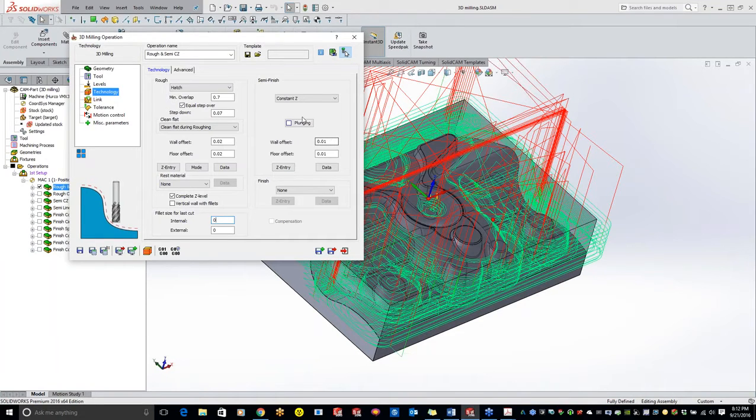Now when you guys do semi-finish, you have a lot of options in here. Doing linear, and as I click through, you can see the pictures change. We do offset cutting, we can do spiral, and I'm going to go through all these operations. I set them up all over here so you guys can see which one does what. Circular pocket.